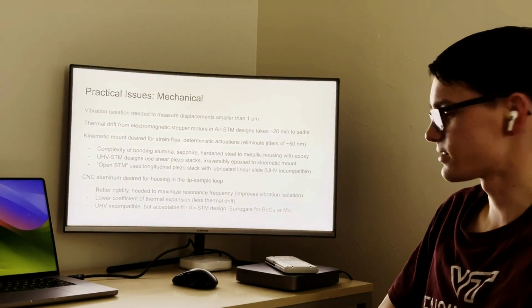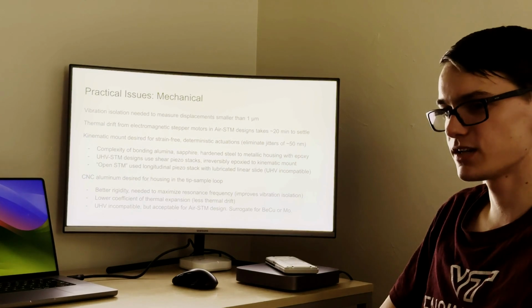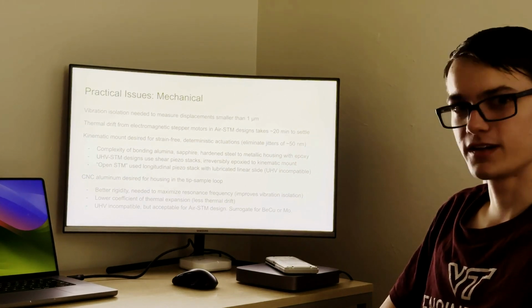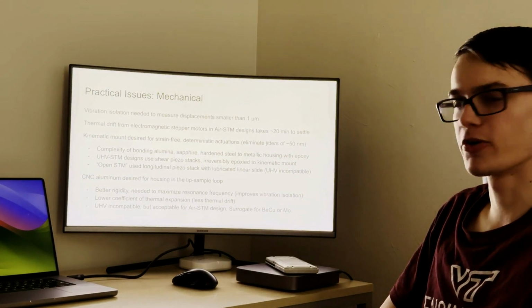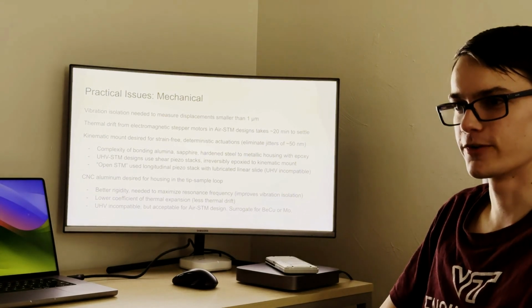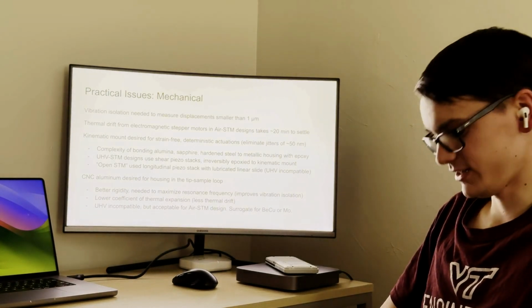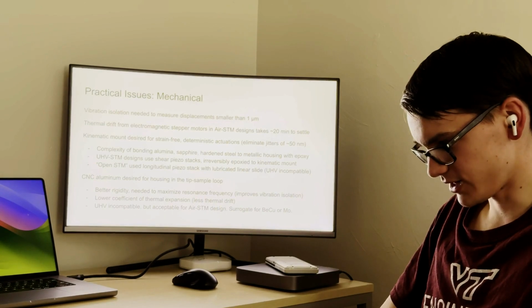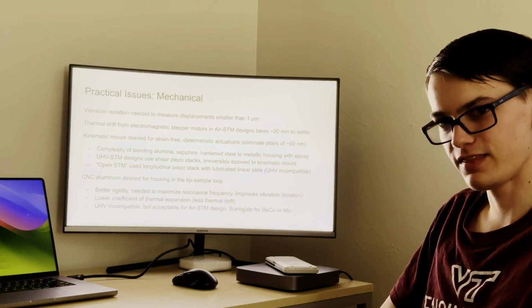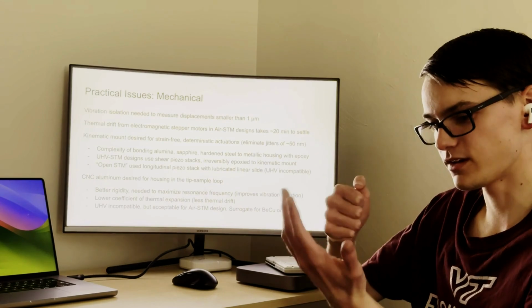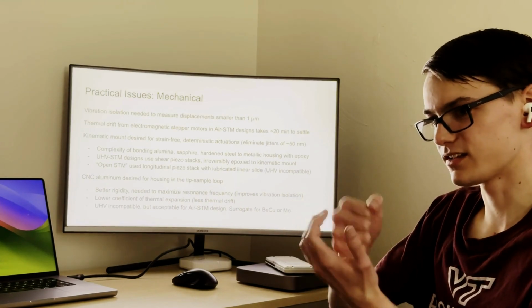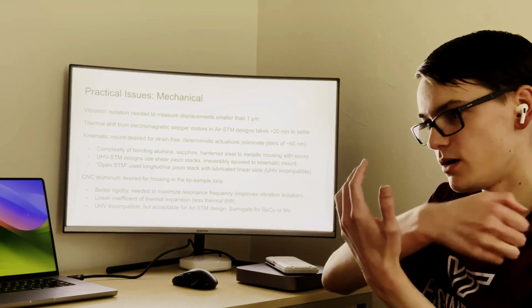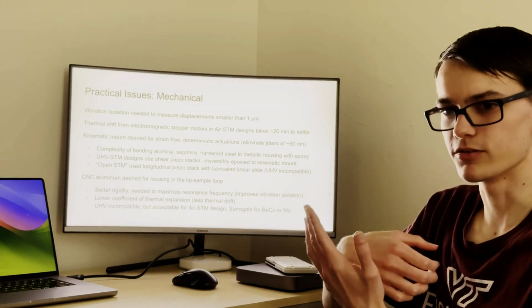A kinematic mount is also necessary for coarse nanopositioners. They'll quote commercial linear slides and some other commercial products for trying to do coarse actuation. They aren't stable. They're over constrained and they have strain. Whenever you move something, it causes strain. And when you try to take a step, it'll release that strain and it'll move something, it'll jolt like 50 nanometers.